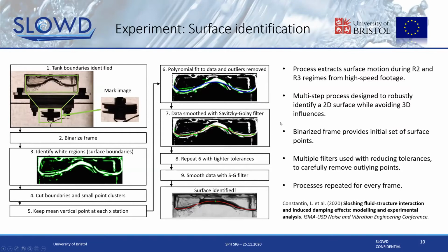And just for completeness, Lucian has developed a technique where we can extract the free surface displacement from high-speed camera footage. He's done this, let me show it here. This is a really good technique, and really helpful for our numerical investigation because we have a direct surface displacement we can compare against. These were just taken from the high-speed setting on his phone, so it's a really handy tool. And we'll be using these later in some of our results to compare the SPH surface motion as well.